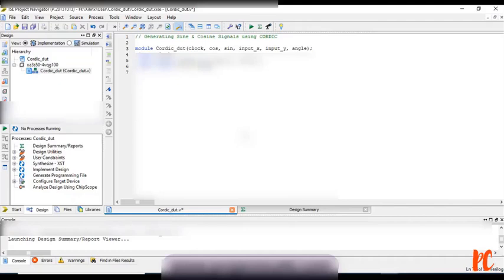Finally, I am going to declare my output parameters, signed followed by width minus 1 down to 0, which is nothing but sine and cos. Since I said I will be dealing with respect to parameter, allow me to write the parameter value, width, followed by, I am giving a constant value of 16 here for a 16-bit operation. Again I need to declare a wire, signed, which is of 32 bits, 31 down to 0.